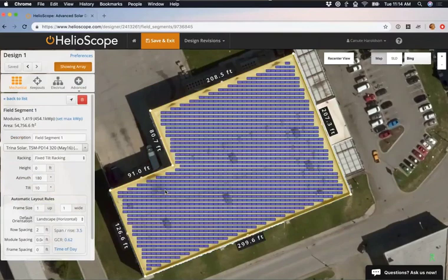That'll make sure that all those lines are actually perpendicular to one another, so I know that I've drawn out this rectangular rooftop and don't have to worry too much about anything else. So if you do have rectangular roofs like this, I highly recommend, once you draw that first line, using Shift and holding that down to make it a lot easier to draw them out.